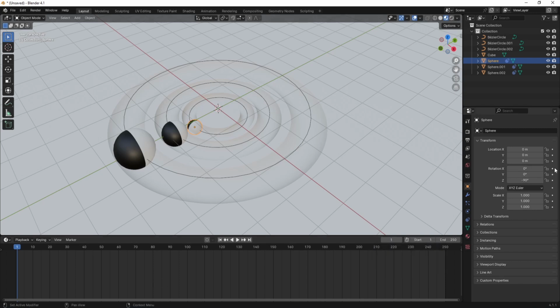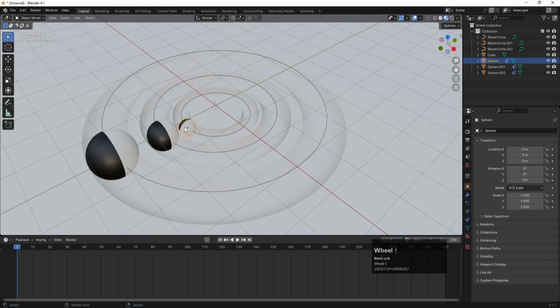Okay, I'm going to create one keyframe at rotation. Make sure that you are selecting this ball first. Let's create one keyframe at rotation, and let's go somewhere around frame 120, and I'm going to make it 360 into, let's say, 4, and create another keyframe over here. So if I see this, I'll get this kind of animation over here.